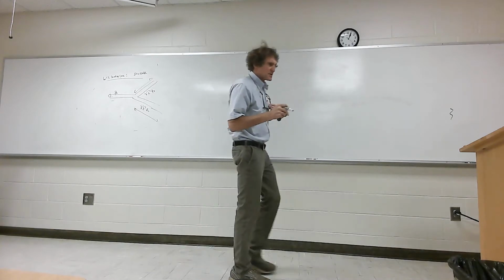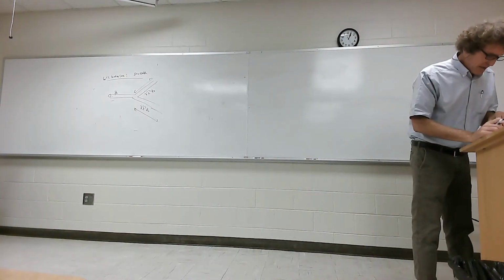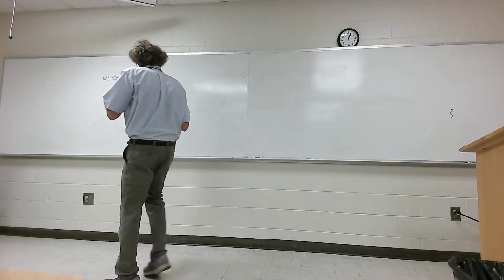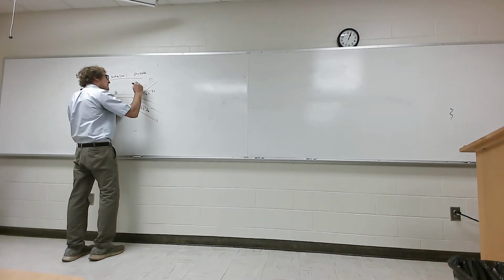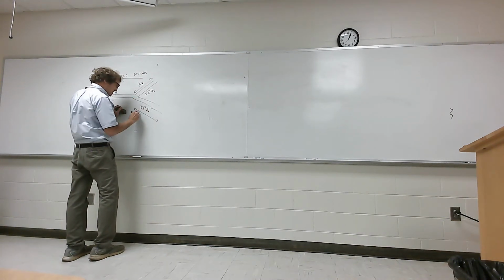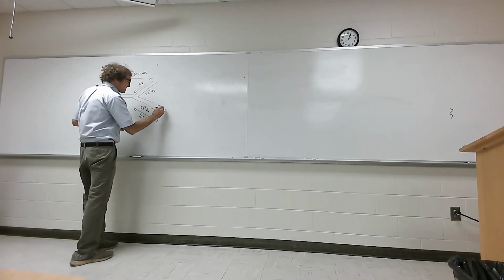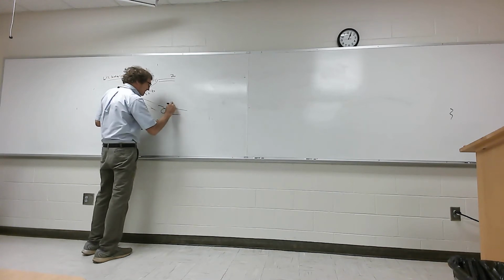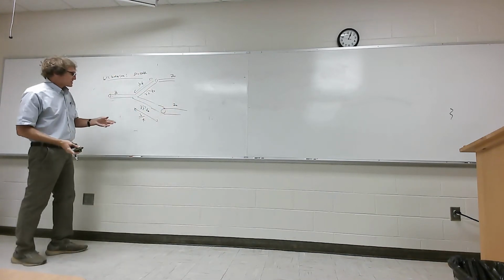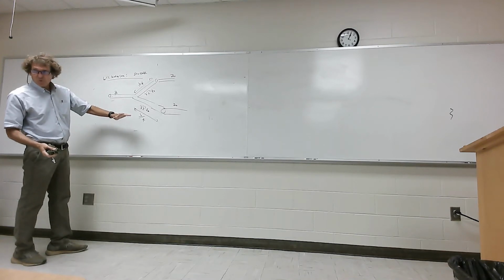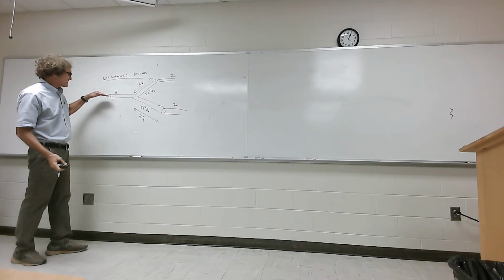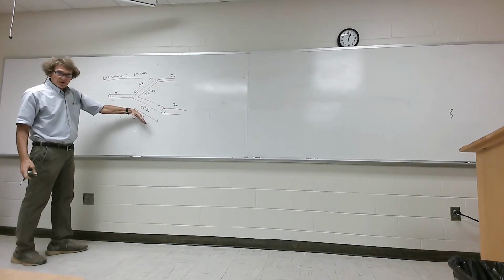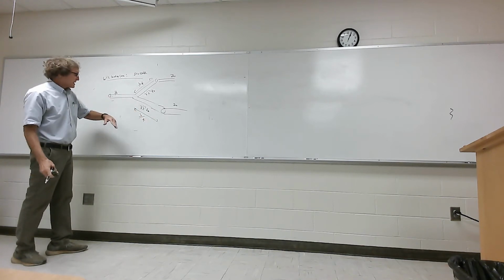Now, he shows a whole transmission line thing, but this is on page 571. And then, coming out here, it just goes to the standard Z0. I didn't show you the way he does it, where he has the upper and lower portion of the transmission line. I'm just showing you, this is the characteristic impedance Z0. This is going to be the square root of 2 times Z0. This is the square root of 2 times Z0. Y'all follow me? And it's a quarter wavelength long.